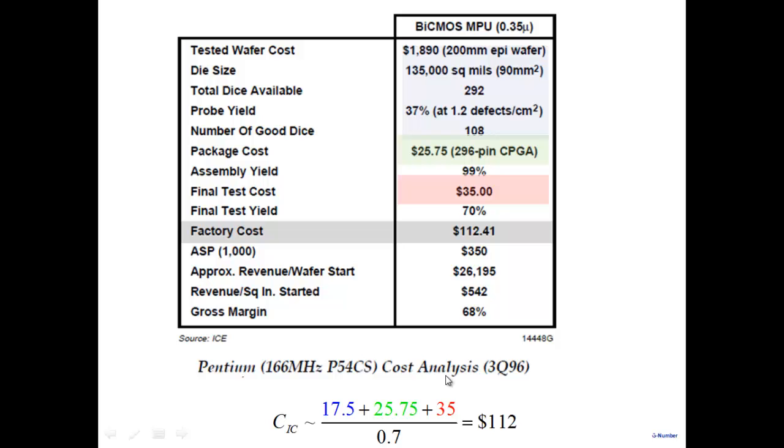And how many such possibilities are there? 2 to the power 8 possibilities for one input, 2 to the power 8 possibilities for the other input. You multiply them together. How many test vectors do you have to apply? A large number of test vectors. And that's only an 8-bit adder. Microprocessor is much more complicated with multiple states and all that, right? If you economize on testing, I'm not sure anybody does that, but exhaustively testing any digital circuit is impossible now. The number of test vectors that you have to apply is so large that you cannot exhaustively test any digital circuit right now.